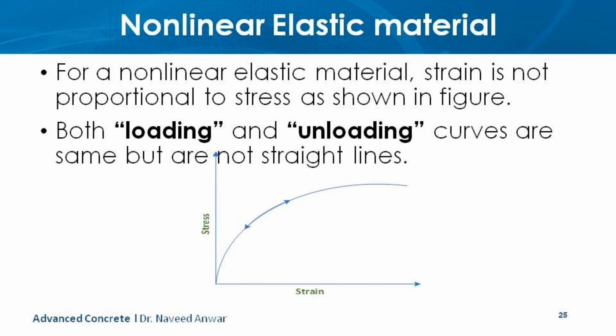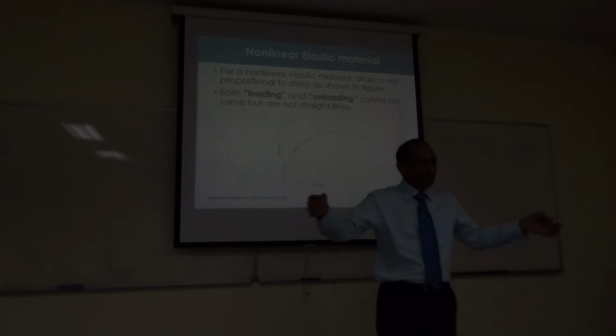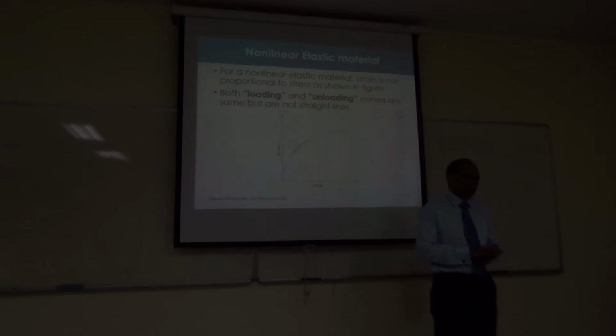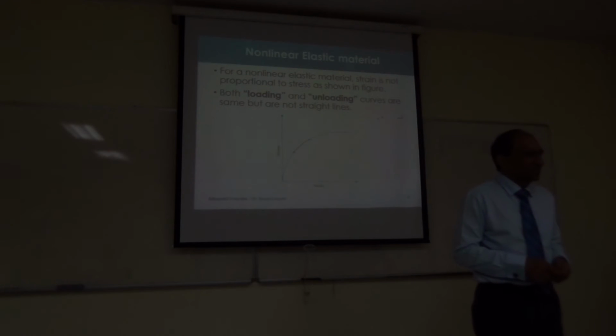Next one is nonlinear elastic. Nonlinear but elastic. That means the relationship between stress and strain is not straight, but it still comes back to the origin. Like that. So of course, rubber, elastic. You stretch it a lot, but leave it, it comes back there, even though the extension is not linear. Right? So many materials are like that. They're very good at behaving in that way. And these do not exhibit any damage. So these materials you normally cannot break by twisting. That's why rubber you cannot break by twisting. Right?